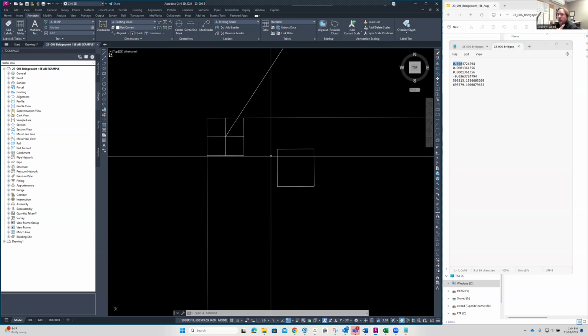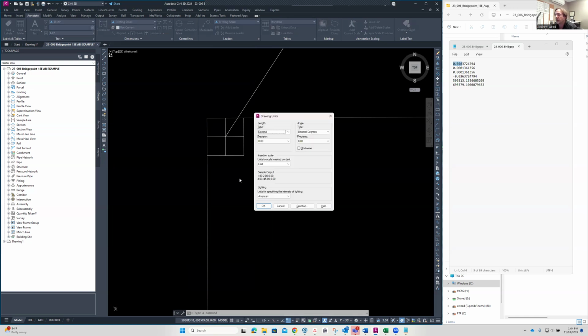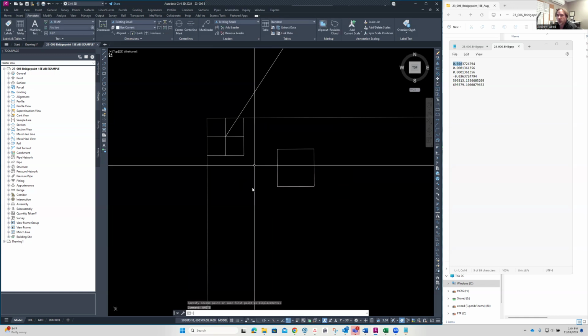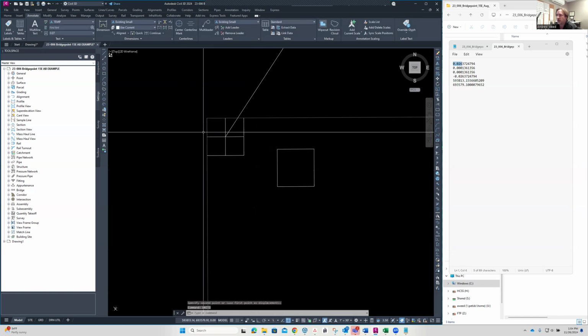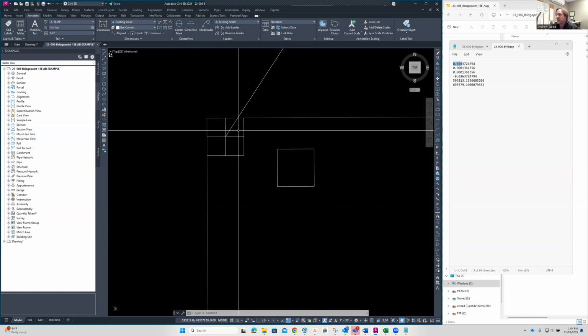But the coordinates are relative. We could have uploaded our project control in meters and then would have gotten our project back in meters. It's just important to make sure you're using the correct coordinate systems and they're the same. So in this case, our drawing itself is set to feet. And that's what our control was based off of, and that's what our drawing is based off of. So this is in the correct place and at the correct size and using the correct units.